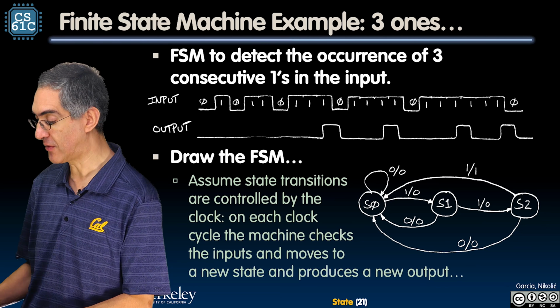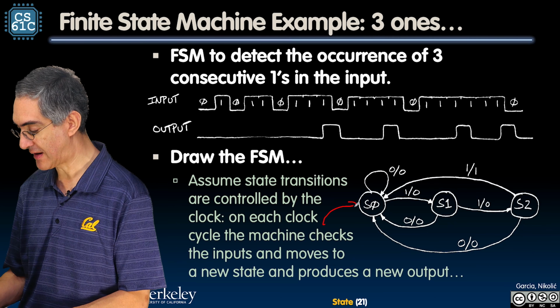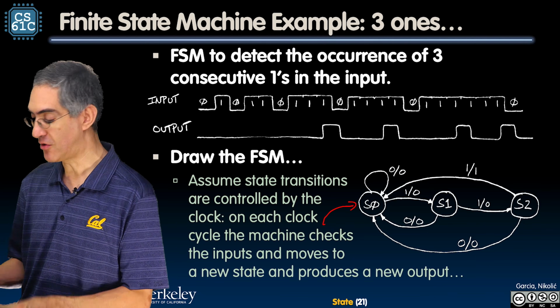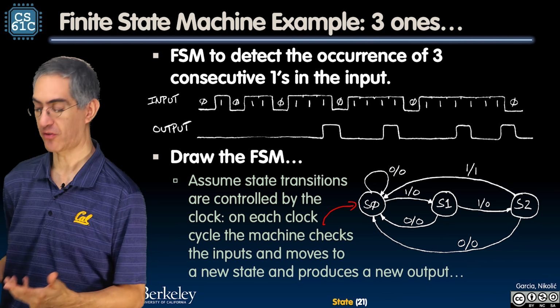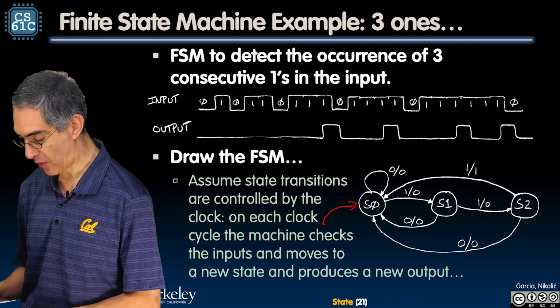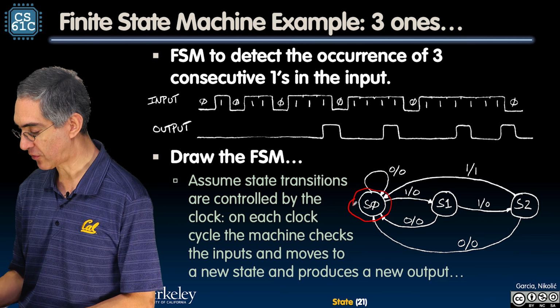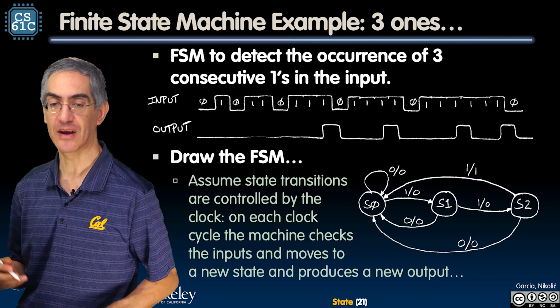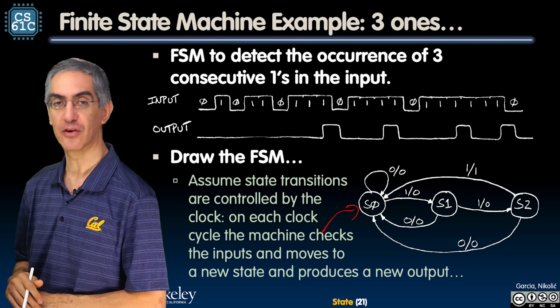The second thing, and I didn't do this, I wanted to show you how to do this. Every finite state machine should have an arrow indicating the initial state. You just can't have this set of arrows and transitions and not know where to start. You've got to know where to start, and usually there's an arrow in, or what they'll often do, I'll just show you this, they'll do a double circle. That's a double circle around that, and that says, okay, that's the initial state. One of those 2 ways is fine. Let's go with the arrow. So it means we're going to start at state 0.